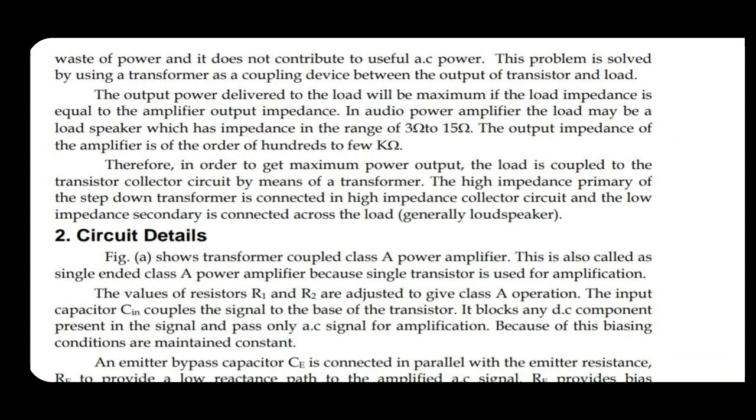The coupling is between the load and the output of the transistor. In between, we have to connect a transformer. The output power delivered to the load will be maximum if the load impedance is equal to the amplifier output impedance.